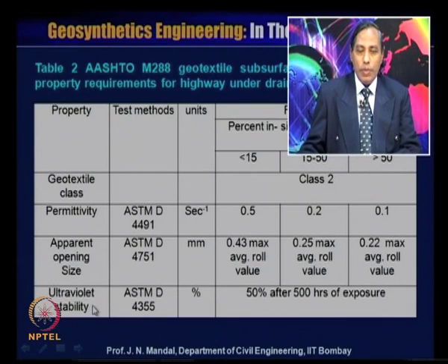And ultraviolet stability is also very important. This is as per test method ASTM D4355 and expressed in percentage. This is 50% after 500 hours of exposure.